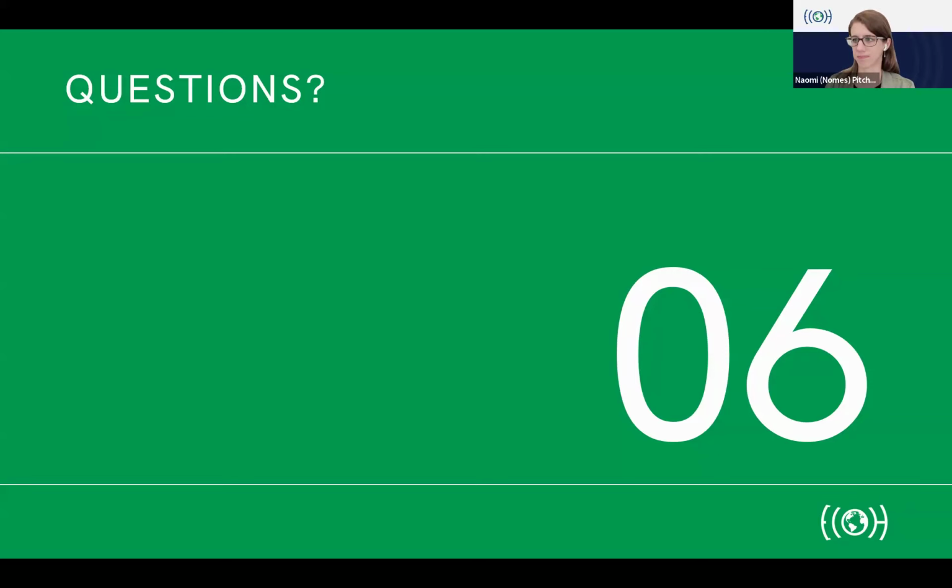Really good question. Well, because when you're ventilating a building, you have to treat a building as a whole, and an unventilated basement can build up moisture and other problems, right? So mechanical engineering and building science has evolved to address mold problems. So it's important to ventilate the basement, especially if it's occupied, because those occupants need air. But radon is strongest or highest at the source, which is in basements. It is a heavy gas, but a typical ventilation system or normal air movement within any building is more than enough to push it and distribute it around.